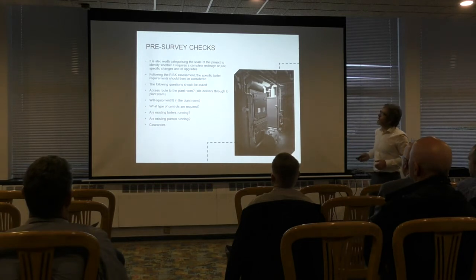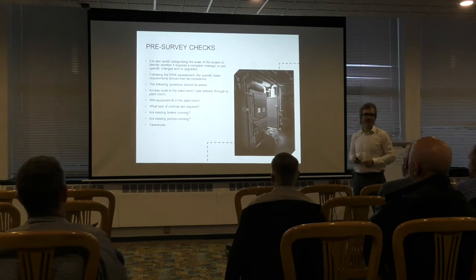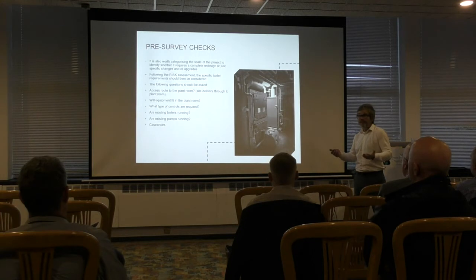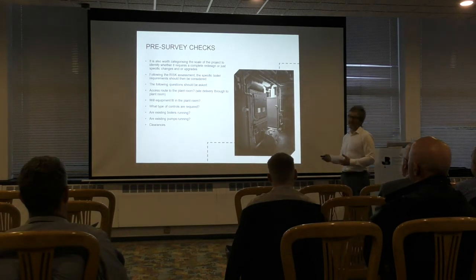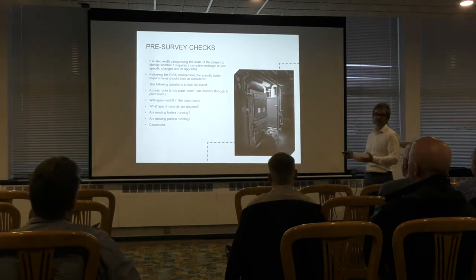Once we've done the risk assessment, it can help in actually narrowing down your boiler selection as well. If you identify by doing a risk assessment that you have got access issues, it could be that at the moment we've got 200-300 kilowatt boilers in there, but we're not actually going to be able to fit 200-300 kilowatt boilers into the plant rooms. We might need to look at putting in some smaller modules. So that can help on the risk assessment.